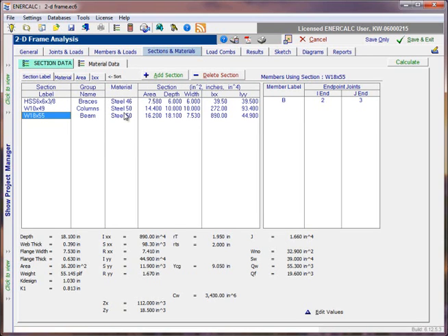First, because it's always possible that that section is fabricated out of aluminum or fiber reinforced plastic. Second, because you saw in this example that even when you select a steel section, that's not enough to specifically define the steel material, because we had a need in this example to distinguish between grade 46 and grade 50 steel.